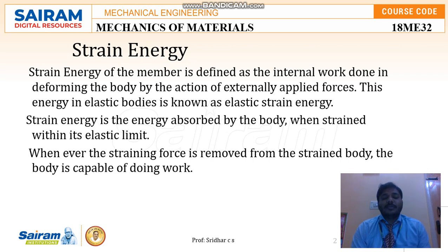Failure depends on whether it is a brittle material or a ductile material, and based on that the deformation will occur. Normally the strain energy is what we call stored energy. Whenever you apply the load, the energy is stored. After releasing the load, because of that stored energy, the body can come back and regain its shape, size or structure.